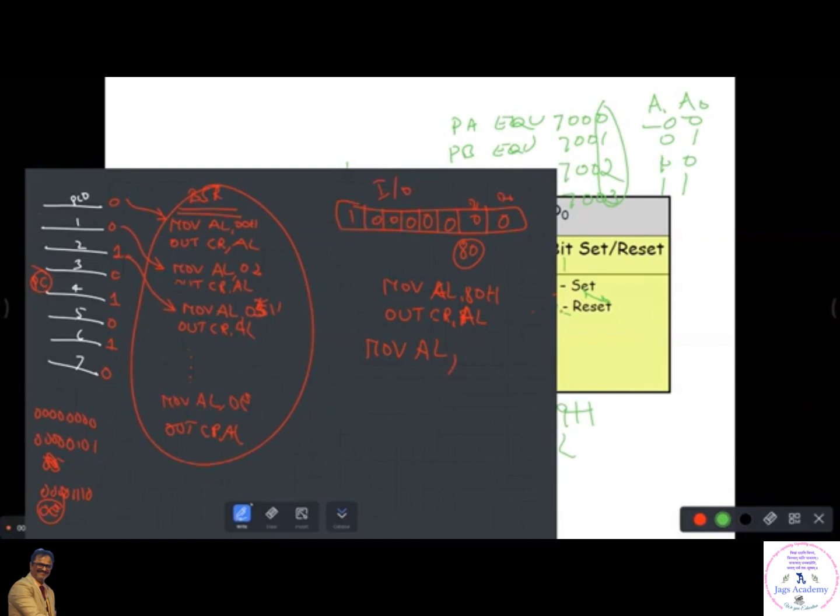This is the upper nibble. It will start from here, right? Yes. So this is 5, this is 4. Now you just put 54H. Just use OUT port C, where port C is the address, comma AL. Done. See, done.